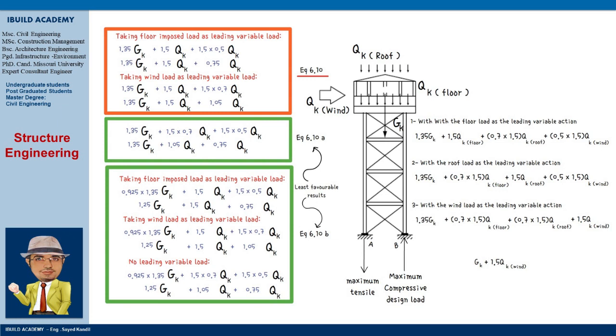For large and complex structures, the theoretical number of possible load combinations can be formidable. However, the experienced designer quickly learns which ones are the most critical. Finally, when checking structures against serviceability limit states, such as deflection or cracking, the loads are usually used unfactored.